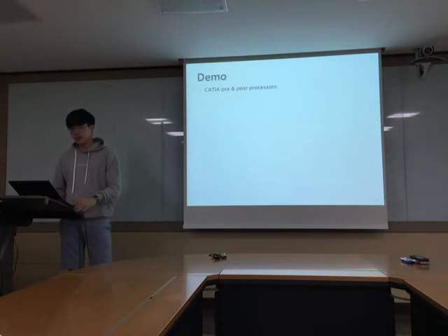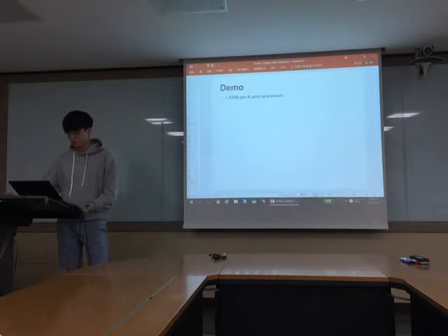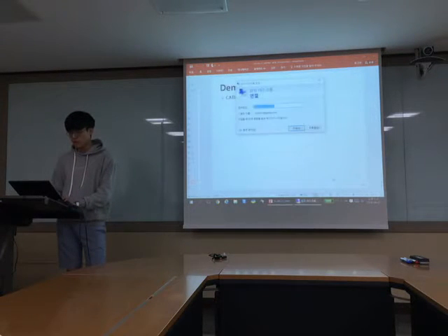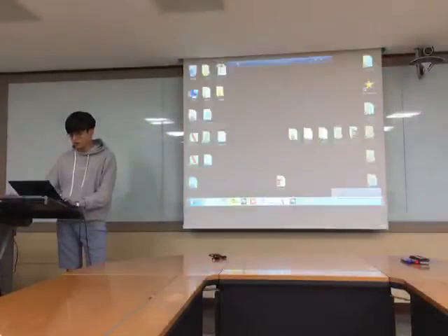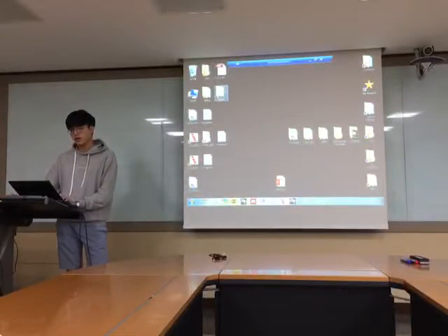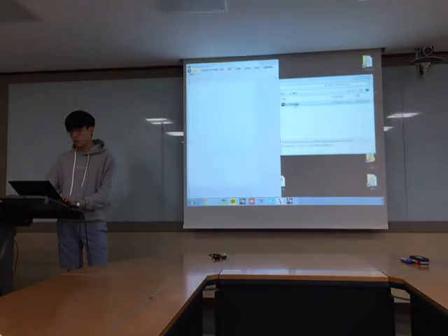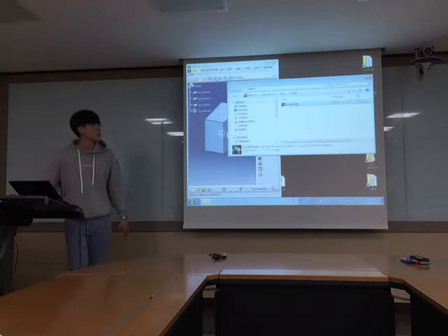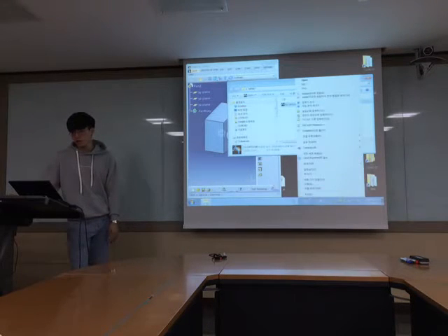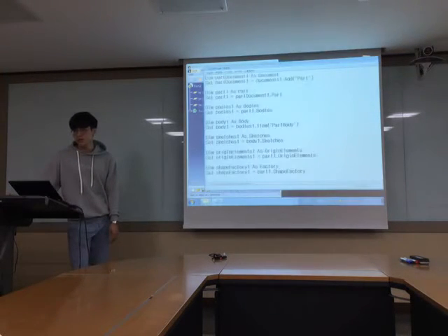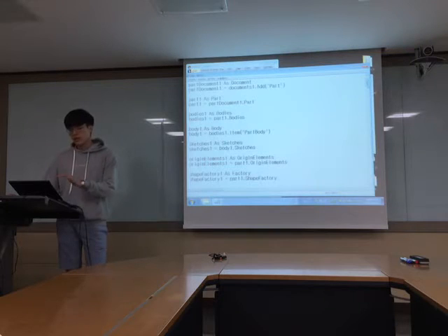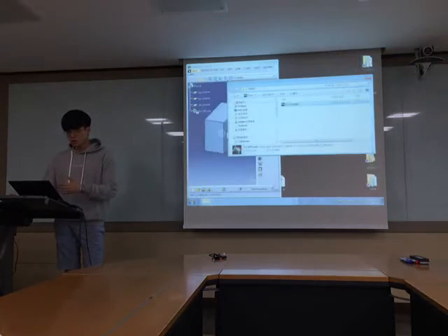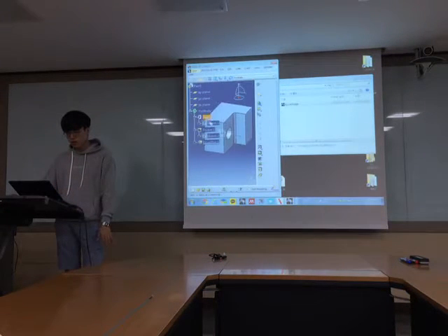I've made CATIA pre and post processors, so I will show you how it goes. You can use any programming language. This is a CATIA script file. If you open it, it is just a text file, which is recorded by CATIA. It contains the feature and procedure. If I open it, you'll see there's information.